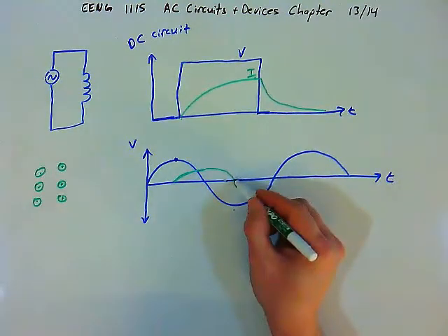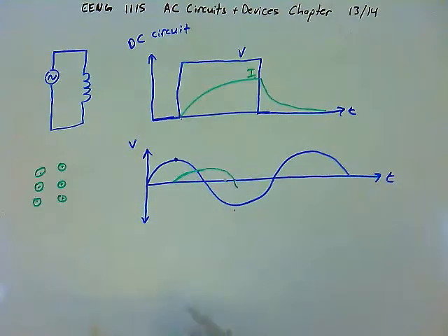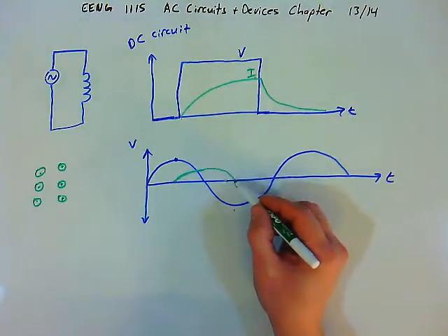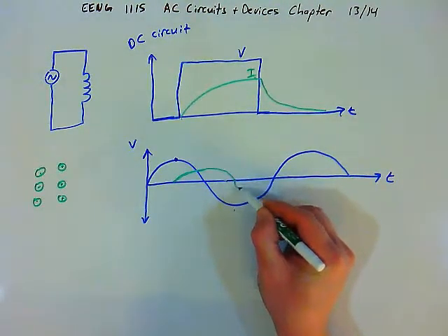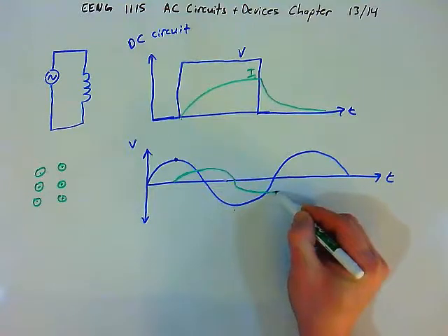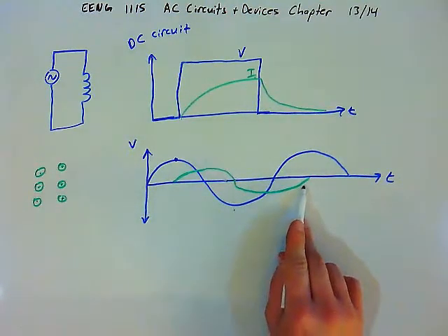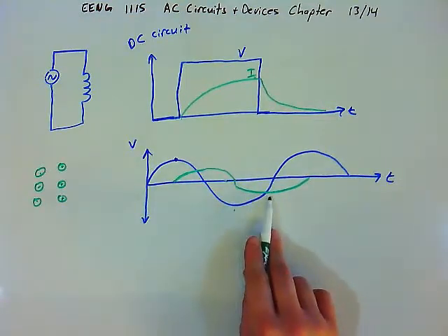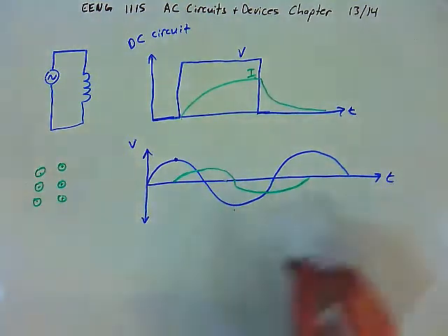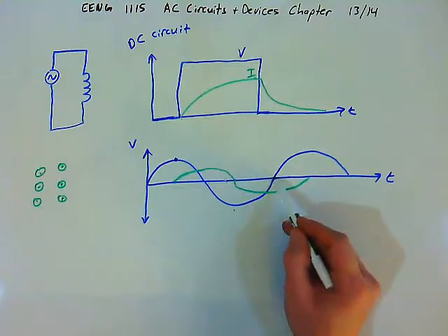And so now the inductor is starting to build up a magnetic field in the other direction, right? All of the polarities have changed. Current's flowing in the opposite direction. North and south poles have switched. Polarities of voltages have changed. Everything's changed, opposite direction. And so the inductor starts to store its magnetic field, this time in the opposite direction. The current is flowing in the opposite direction through the circuit. It's growing its magnetic field. It's storing energy. And again, at the point when the voltage reduces back to 0,